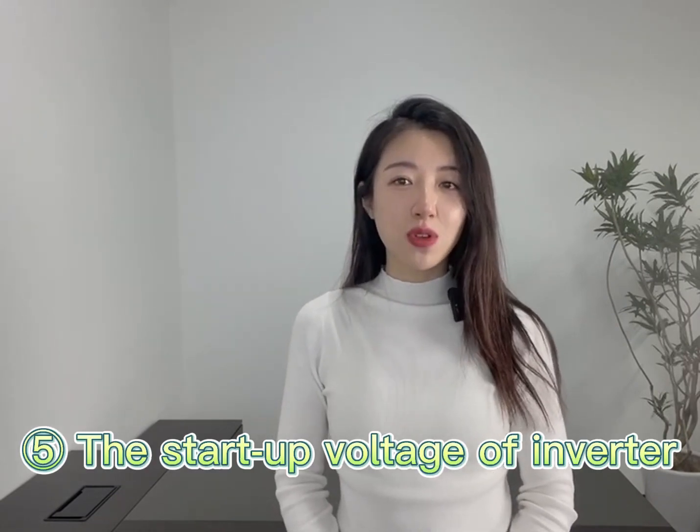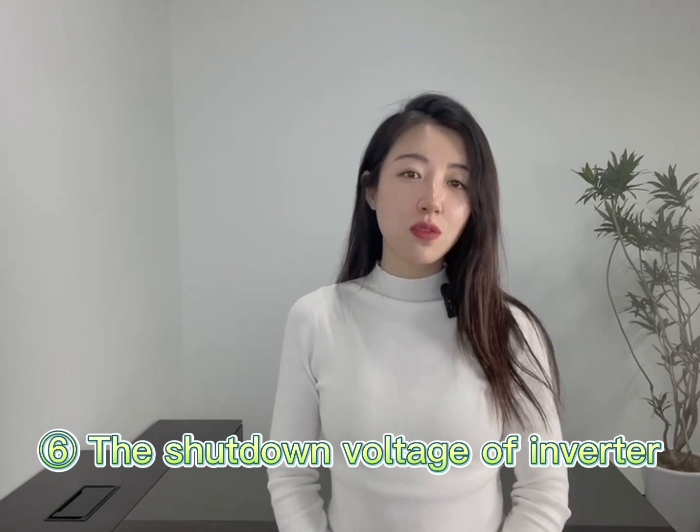5. The startup voltage of the inverter. The inverter will start working when the highest voltage of DC input strings reaches the lowest starting voltage. 6. The shutdown voltage of the inverter. When the output current and the voltage of DC input strings become weaker, which results in the output power of the inverter being close to zero, then the inverter will stop working.